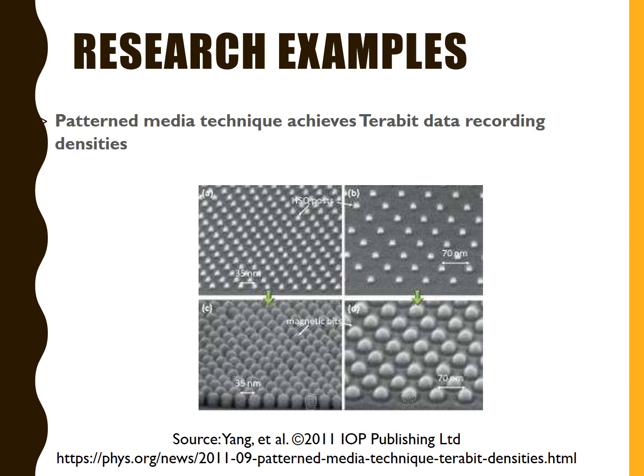So a group of randomly oriented magnetic nanograins arranged in a thin film magnetic alloy gets implemented, and after that they do the entire imprint. Okay, this is how you do the process using nanoimprint lithography.